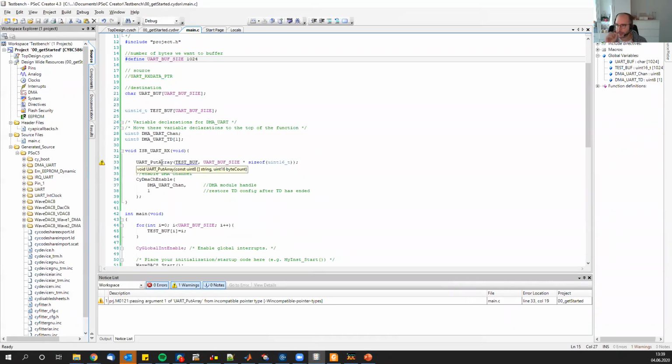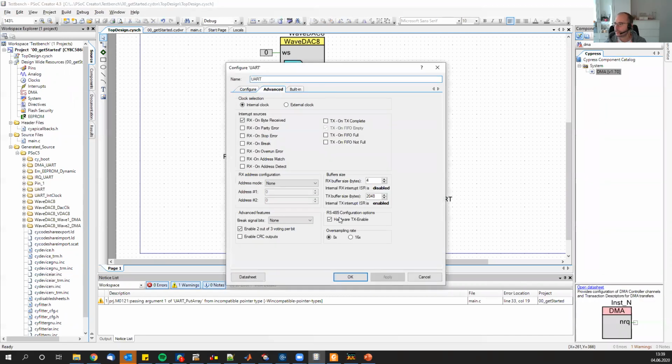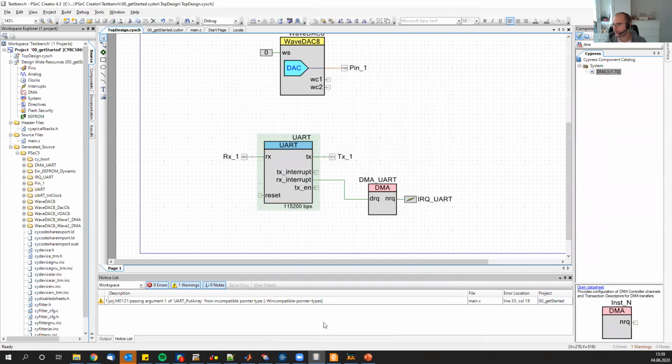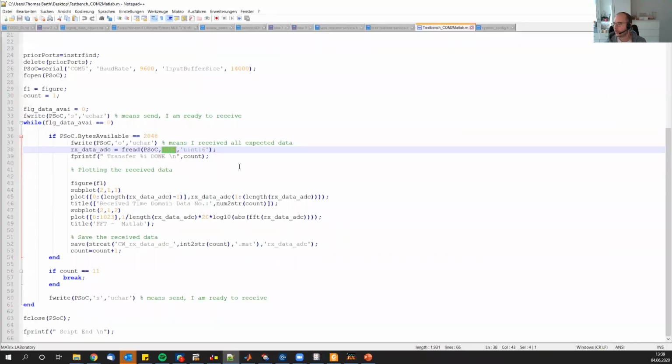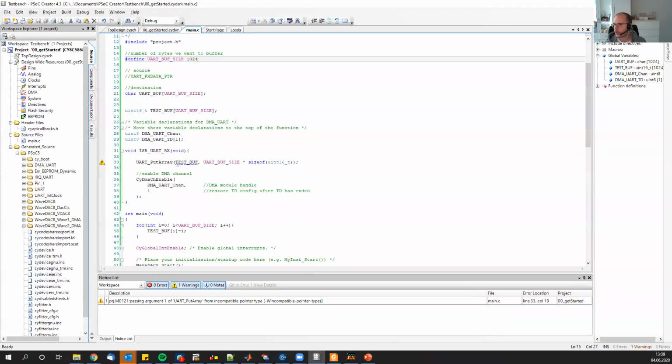Yeah. So now it's 16-bit. Okay, this is better because, so important, we need to set the buffer size here to a big value, right? So I propose to at least make it so big that all the data can be pumped in a single request or a single transaction, so that this function here also accepts a higher byte count.